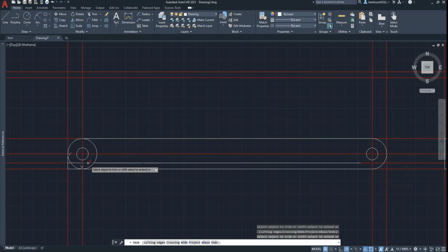Okay, like so. So 1, 2, 4, 5. Now what I need to do is offset 125 to find the centre point from the 250 line, which is there. Offset now 110 either side, so I can get the profile for the trim. Wasn't far off.